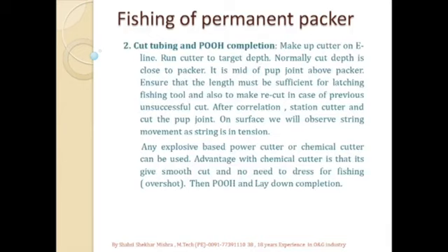So once the surface preparation of the cutter has been done, before that we will run the dummy to see the tubing and the completion is clear from the inside, of the same size of OD as the cutter. Then we run the cutter and do the correlation log. Then we place the cutter at the cut point above the packer.